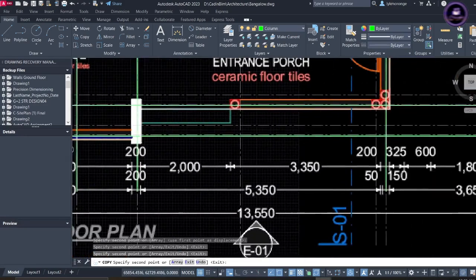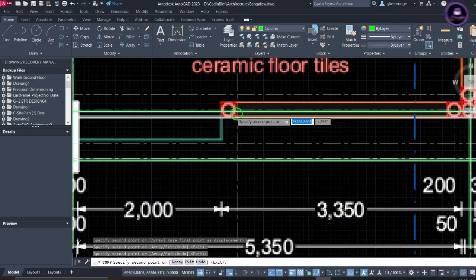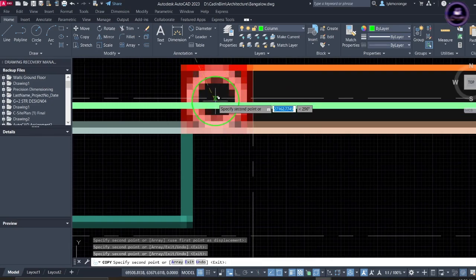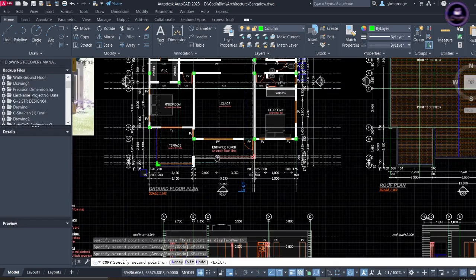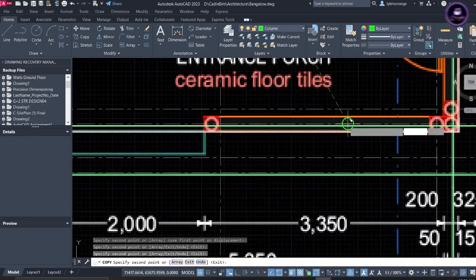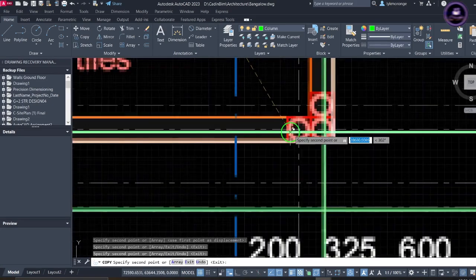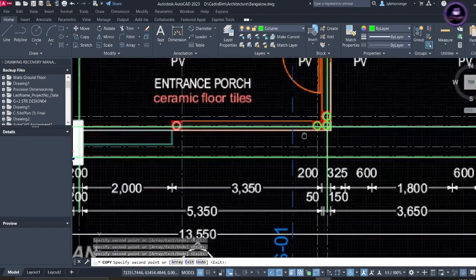And also let's come and add this. Did I actually create some circle here? You can see these are the corner here. There is no grid, so if there is no grid, remember that column will not actually be identified in ProtaStructure. So that's why we actually need a grid here. So I'll just put my grid and then I just come and place it. So let's just have this. We also have this. We also have this. So those are the columns.